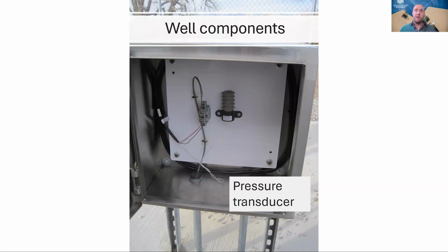And it's really important to know what this is because you want to make sure your pump is in the water. If you're in an area experiencing drought, perhaps that water table is dropping down, and it's possible that your pump may no longer even be in your aquifer. So it's an important thing to measure. Or it could be in that aquifer, but then when you turn it on, the drawdown could be so much that it sucks air. And of course, you don't want that.